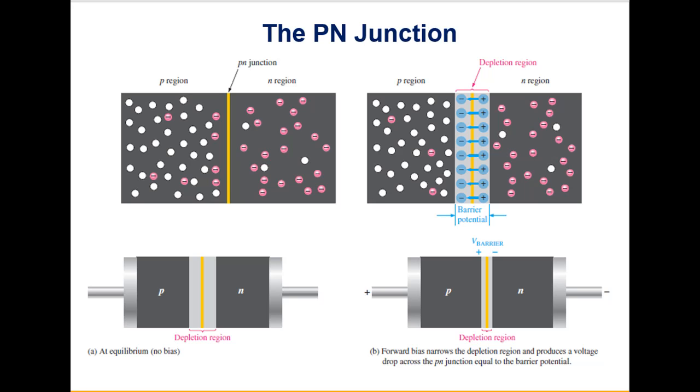To make intrinsic semiconductive material more negatively charged, or N-type, the element antimony is used because it has an excess donor electron, making the material negatively charged. To make the intrinsic semiconductive material more positively charged, it will be doped with P-type impurity. Usually boron element is used. Boron atoms lack a spare electron, therefore it has a hole and is positively charged.